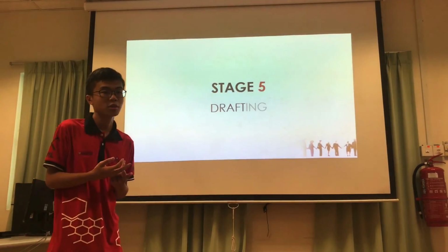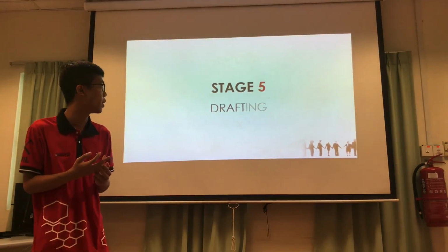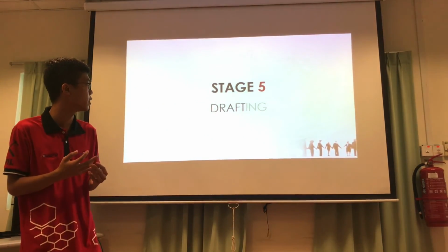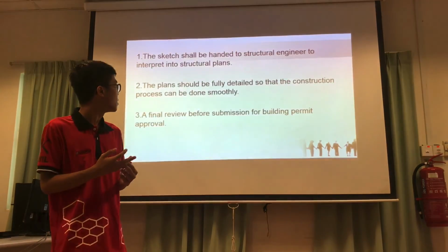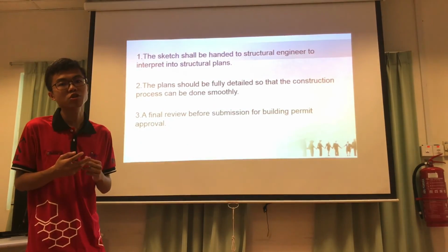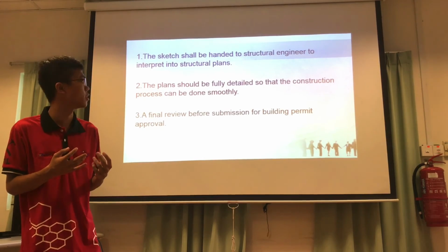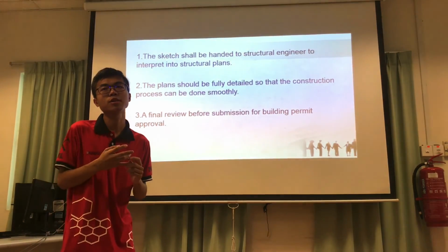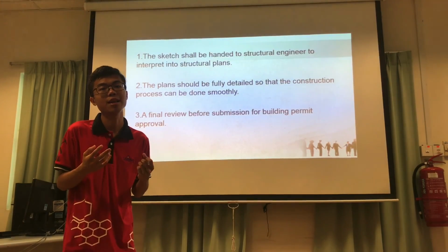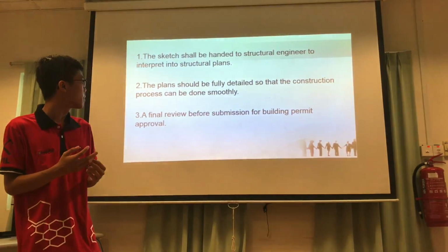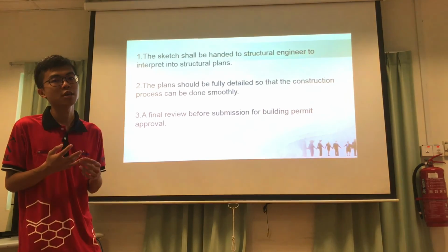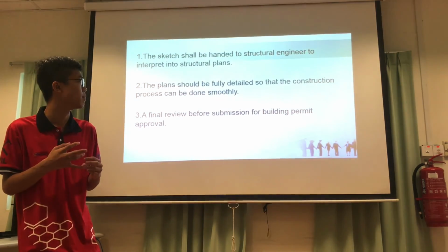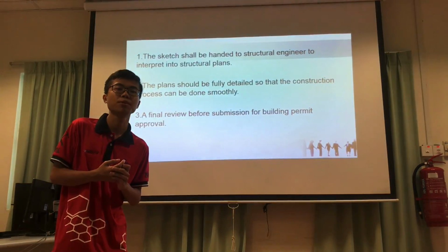And next, we continue the discussion with the fifth and final stage, which is the drafting phase. In this stage, the sketch will be handed over to the structural engineers for the final interpretation. The plans should be fully detailed so that the construction on the site can be done smoothly without any delays. Last but not least, a final review by the structural engineers will be done before the submission to the authorities for the building permit approval.